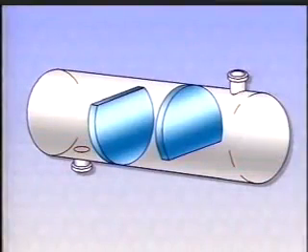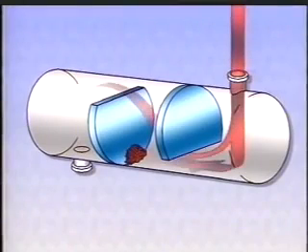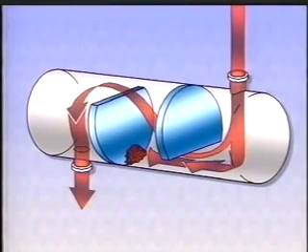Segmental baffles can direct the flow to be horizontal or vertical depending upon the fluid being used. If the liquid is dirty, the sediment will often build up behind a horizontal baffle. This decreases efficiency by blocking the flow.